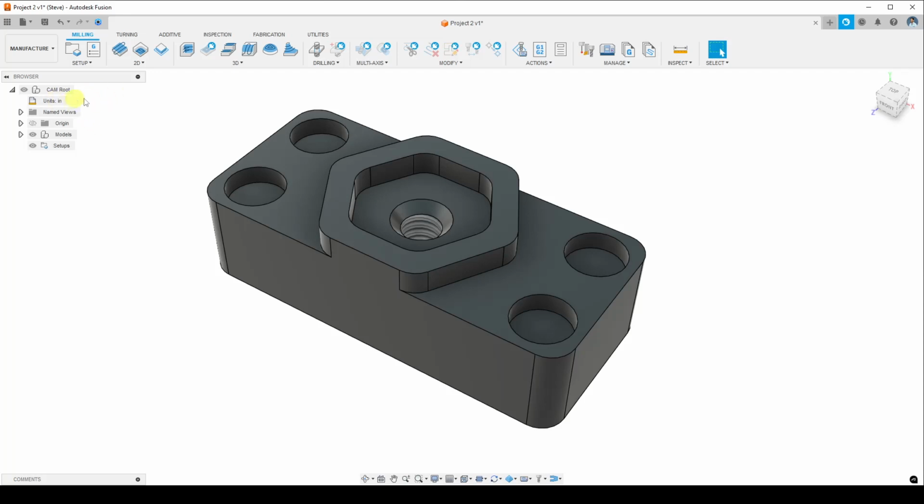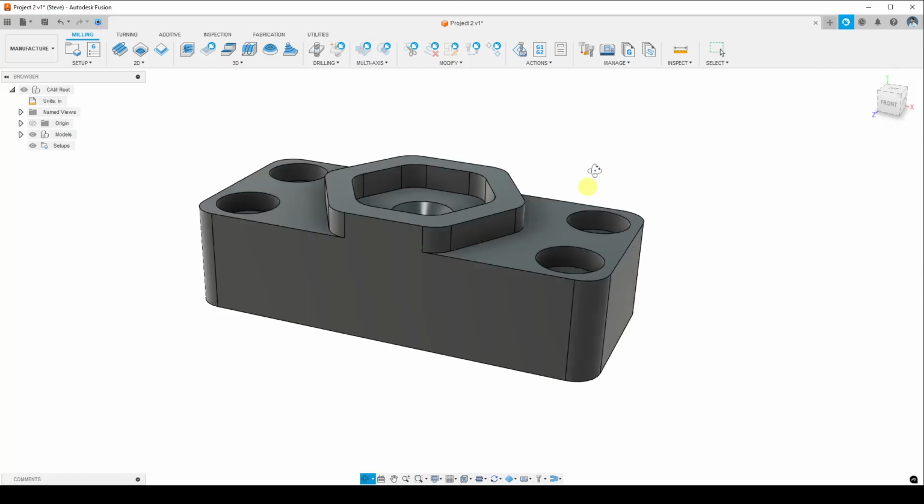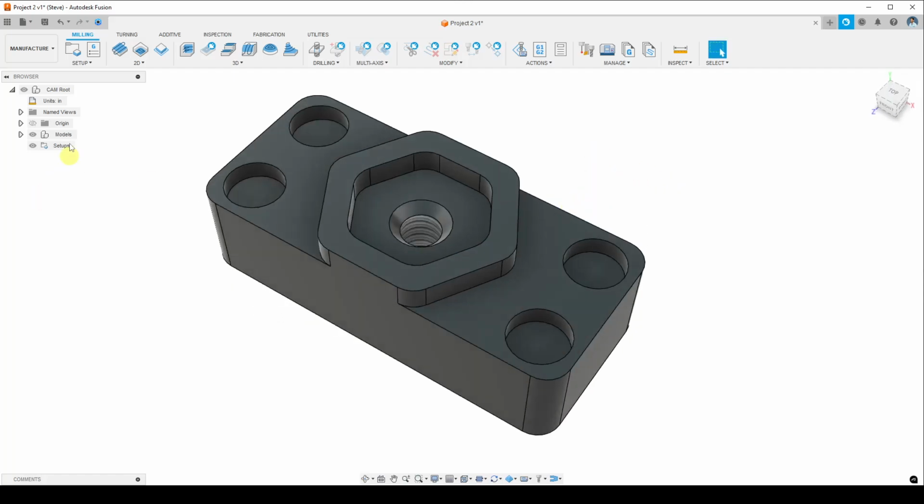There is an option at the very end when we're making the G code to change the units of the G code. So you can actually work in inches in this environment and then export your G code in millimeters if that's how your machine works. The important thing is just to know that there's a difference and that you have to specify at some point. Okay, so we are in inches.